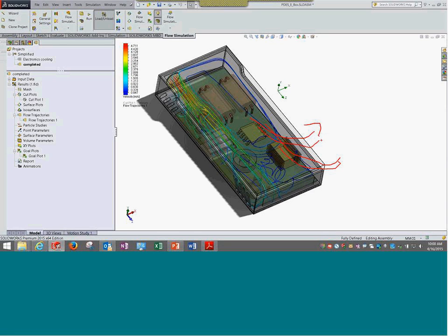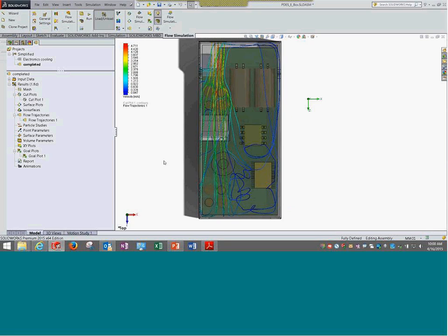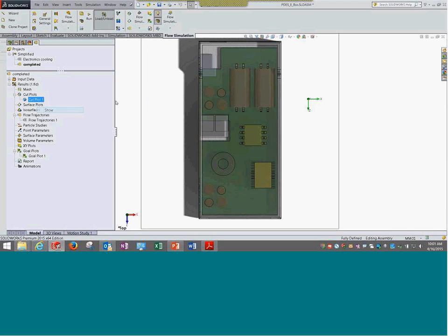So assuming that I cannot create any fans here because of the design requirements, probably I relocate this heat sink over here, maybe I have a restraint and I cannot create holes here. I can relocate the heat sink internally somewhere on this side and utilize it. Or even this location would be perfect, wherein it blows in and takes the air out. All this area is there. Definitely, this gives an idea on what I can understand and how I can play with the setup to improve the design. Let's go back to the cut plot, how it looks.